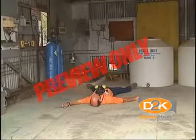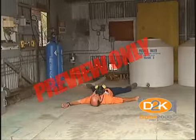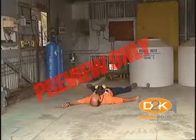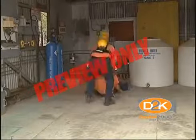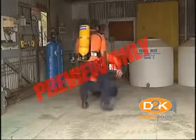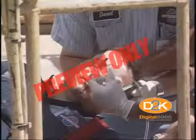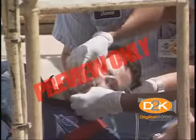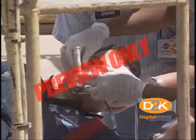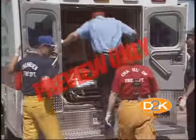What should I do if someone becomes ill from breathing chlorine? Take proper precautions to ensure your own safety before attempting rescue, such as wear appropriate protective equipment and use the buddy system. Remove the source of the contamination or move the victim to fresh air. If breathing is difficult, oxygen may be beneficial if administered by trained personnel, preferably on doctor's advice. Do not allow victim to move about unnecessarily.